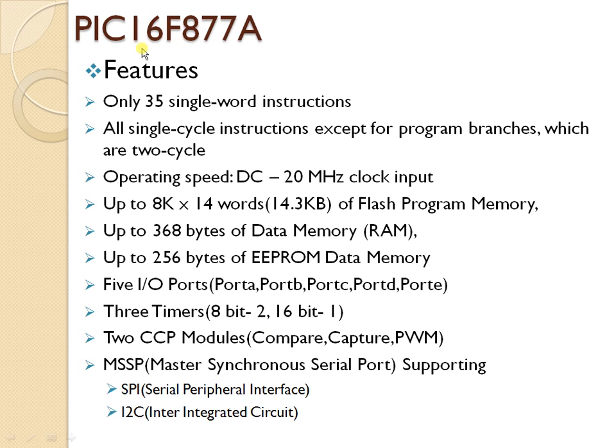So PIC 16F877A is the controller which we are going to discuss. Initially we'll start with its features. As you can see, it has a total of 35 single word instructions. I'll talk about this word in later sessions. Most of these instructions will be executed within one single cycle, except instructions like jump and loop instructions, which will take more than one cycle.